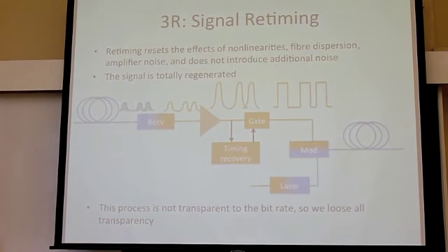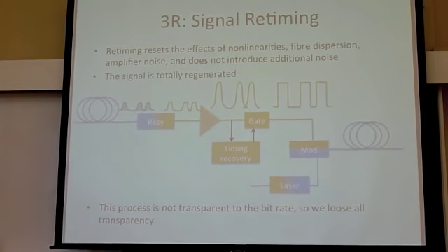Now this is actually quite important because what's the problem here? When you have amplifiers, there might be a situation where you realize, okay, my signal to noise ratio is too bad. I cannot go ahead putting an amplifier. So the only thing you can do, before it deteriorates, is stop the signal. Maybe you get a bit error rate of 10 to the minus 15, which is quite low. And then you can reinitiate the signal. And then what you do, you basically just sum up at the end of the link all the bit error rates. It's like basically having a new link. And then you realize how much bit error rate you have there. Okay, the link is terminated, you write it aside, and then you start calculating for the next one.